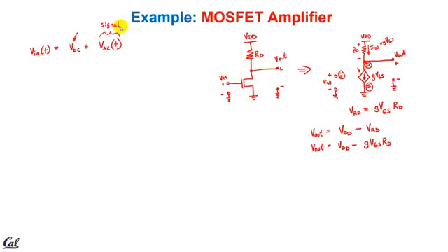All right. But you see the reason, I want to make sure you link it to, we needed to make sure this thing was saturated, right? So if we provide a DC input, forget about the thing on the right. If we just provided the DC input, we assure that we have some constant thing on the output running through. It pushes the output into the saturation region. That constant output current and constant output voltage perhaps isn't interesting to us. That's right. Because the signal is the small AC, but we need it. We need it. And then we're going to have to get rid of it, but that's okay.